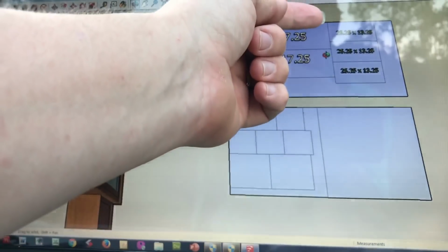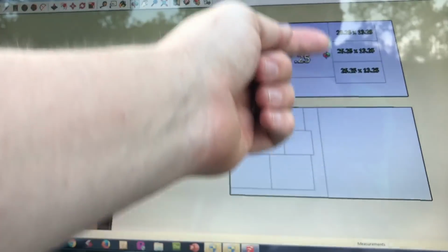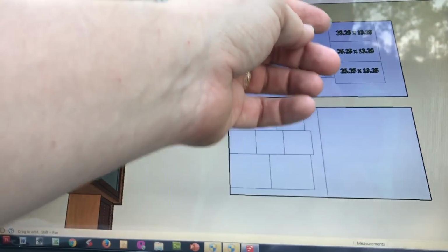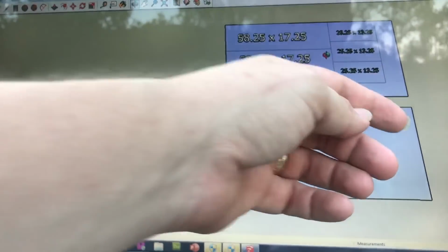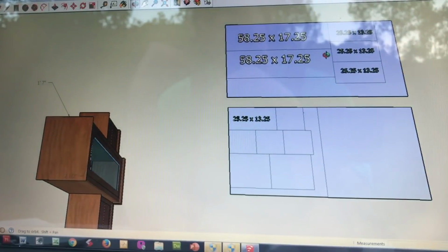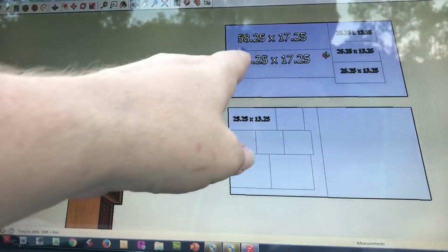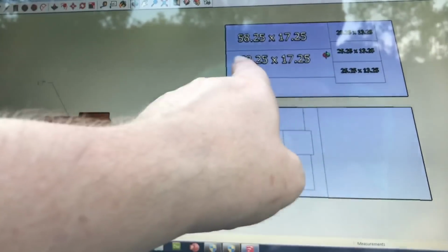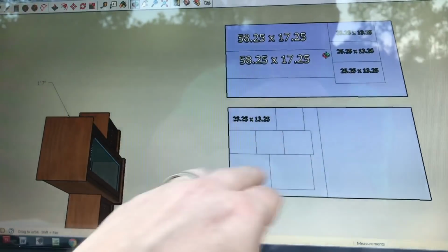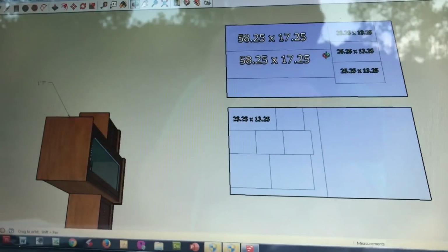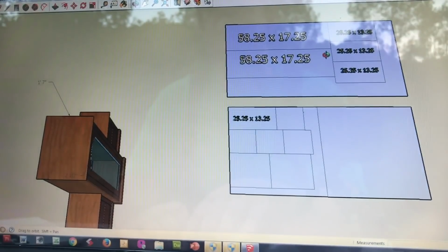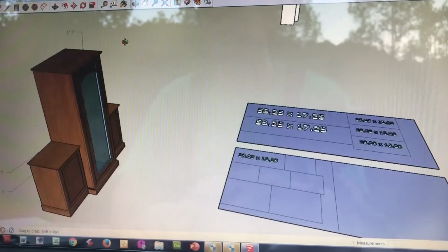So I would do some cutting sideways using my plywood table saw, my cabinet saw. Goodness, I cannot talk. Using my cabinet saw, do my horizontal cuts. I knew when to put a cutting blade instead of a ripping blade on it for my veneer. And then, of course, turn and get my rip cuts out with the grain of the plywood. And then the second plywood sheet, all the pieces that I needed, and knew that I'd have half a sheet of scrap left over. So it was really handy to help me not only design and get an idea of what materials I needed, but also help me with a cut strategy.